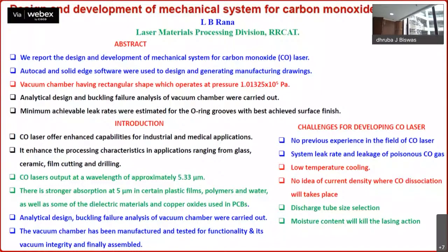My topic is design and development of mechanical system for carbon monoxide laser. The objective is to report the design and development of the mechanical system for the carbon monoxide laser. AutoCAD and Solid Edge software were used to design and generate manufacturing drawings. The vacuum chamber, having a rectangular shape, operates at a pressure of 1.01325 × 10⁵ Pascal, that is atmospheric pressure. Analytical design and buckling failure analysis of the vacuum chamber were carried out. Minimum achievable leak rate was estimated for the O-ring grooves with best achievable surface finish.